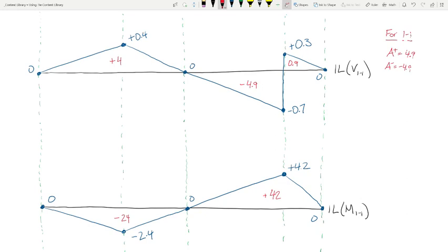Where do we apply that? Everywhere. That's exactly right. It's a dead load. It's not moving. And so we're going to assume, unless otherwise noted, that this is a distributed load to be applied everywhere. So this is our dead load. And what we're interested in is the shear right here due to that load.